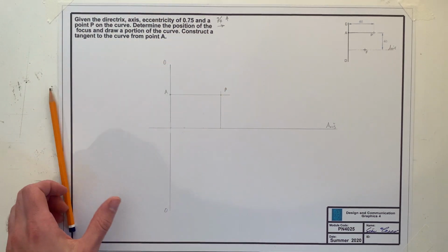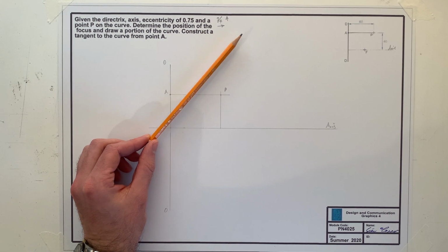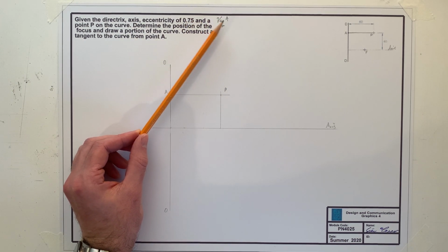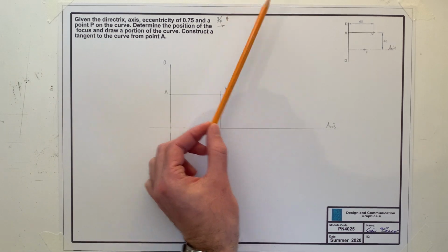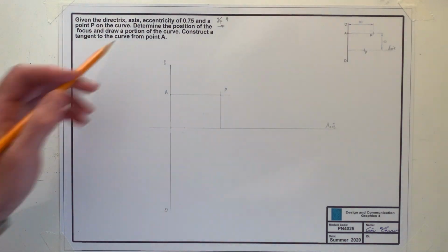Now this can be used no matter what. If you have your hyperbola, remember we always draw an eccentricity line of 45 degrees. The thing about 45 is it's the same, 1 is the same as 1 over 1. So if you went over, let's say 10 here, went up 10, that's where you'd find your 45. For when you're dealing with less than 1, you have to deal with the fraction here.